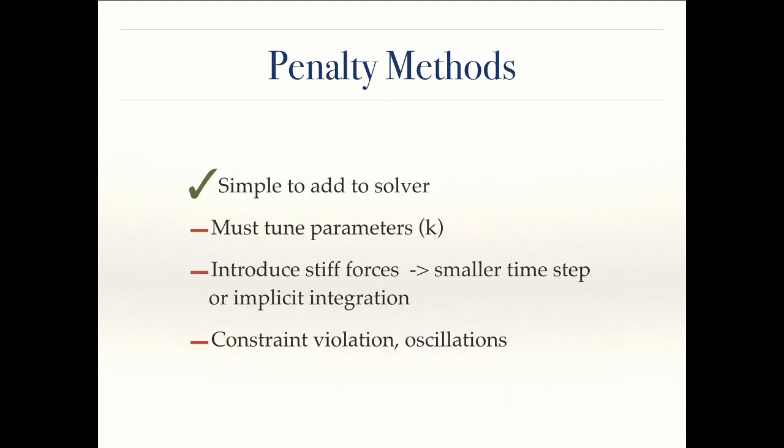And this can get kind of complicated when you have many different constraints in your system, and you have to pick these stiffness parameters for the different constraints, and they compete with each other. And it can become difficult to tune these parameters. Generally, we don't really like to have too many parameters in our simulations that are non-physical parameters. Physical parameters are fine. We can possibly look up a value for them for the material we're trying to simulate, but non-physical parameters, we don't like to have too many of them.